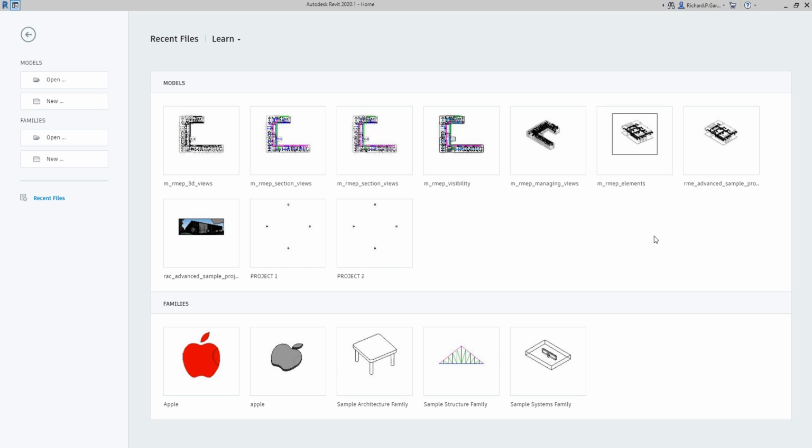The display settings in a project file define the appearance of the model in the project views. You can customize these display settings by changing the default settings of a project based on your requirements, which is what we are going to do.